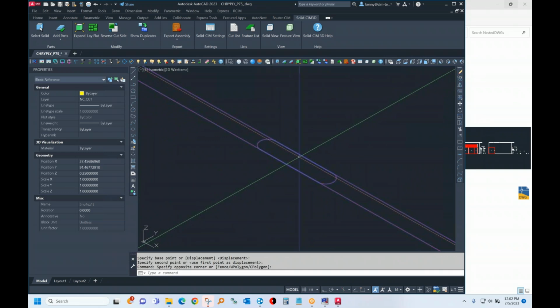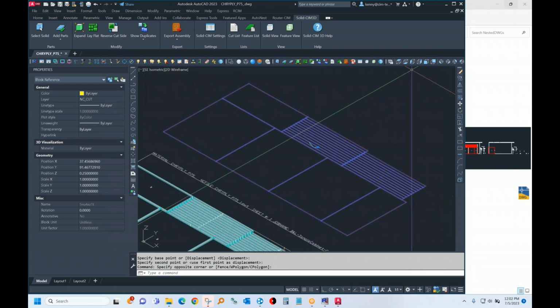Before it used to start and stop in the same spot, and that would make a bump on the part. Then we created an overlap that helped with the bump, but the tool had to stop, change direction, and turn. Now it comes along and does a nice tangent arc in and a tangent arc out to the next shape. And this is so much faster by this small little arc that the machine is very smooth to connect from part to part. One lead in, one lead out. That's a tool stay down type of nest.